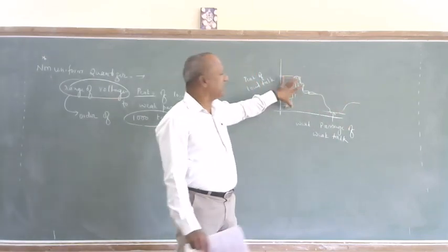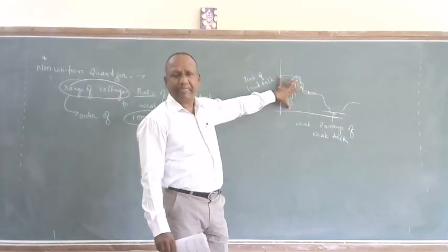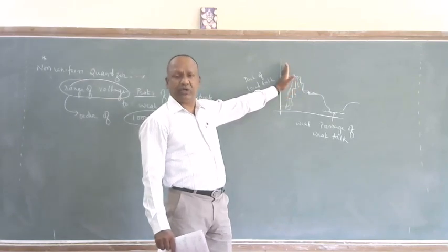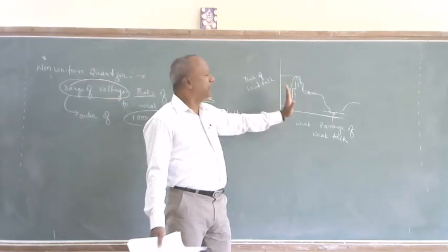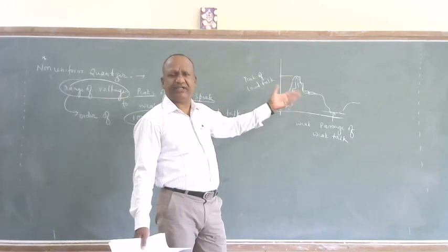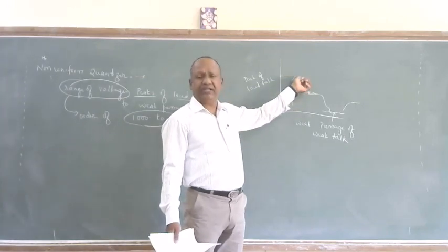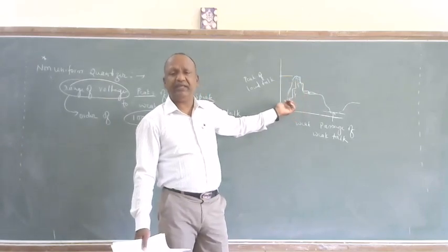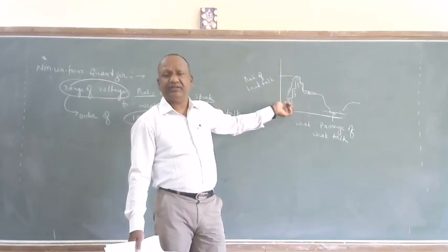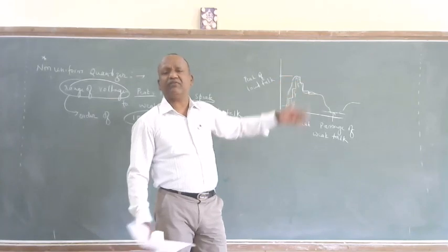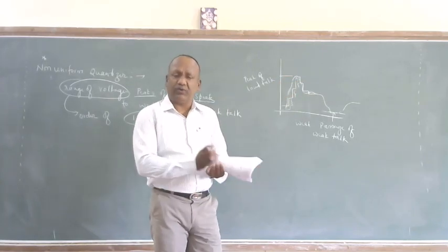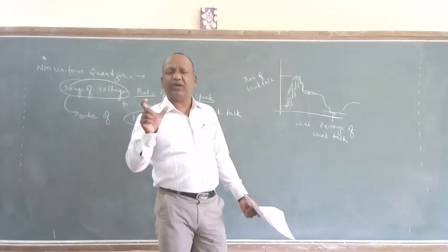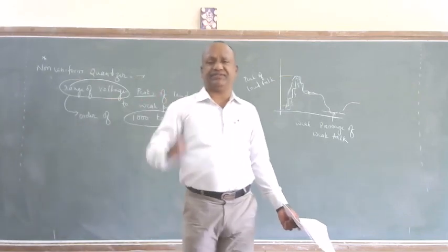But in this case, the information is very less, the amplitude is increasing because of the situation, but the information is almost the same. So to cover this higher excursion of voltage with fewer quantization levels, I have to go for a large step size.